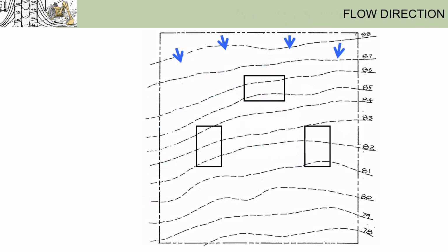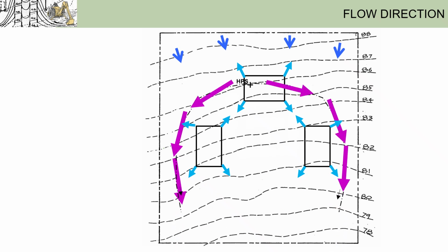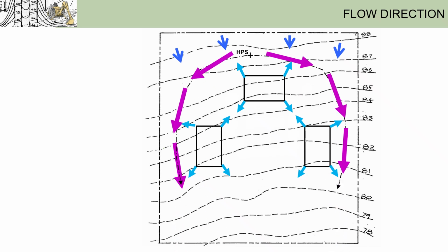Seems very complicated, right? But let's think about where you want water to flow first. First, of course, you'd like the ground around the buildings to slope away, creating positive drainage, right? And then next, just like grading for a single building, let's treat the three buildings as one big group. So you'd have a big swale on the high side of this group of buildings to run water across the site. And lastly, the areas in between buildings will enter into the big swale or flow downhill.